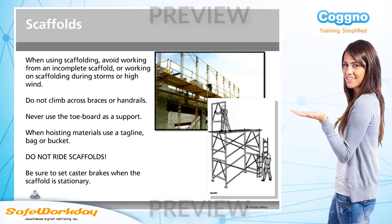Scaffolds. When using scaffolding, avoid working from an incomplete scaffold or working on scaffolding during storms or high wind. Do not climb across braces or handrails. Never use the toe board as a support. When hoisting materials, use a tagline, bag, or bucket. Do not ride scaffolds. Be sure to set caster brakes when the scaffold is stationary.